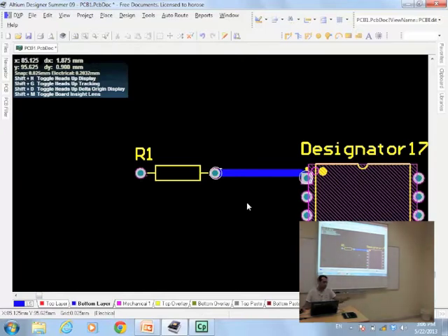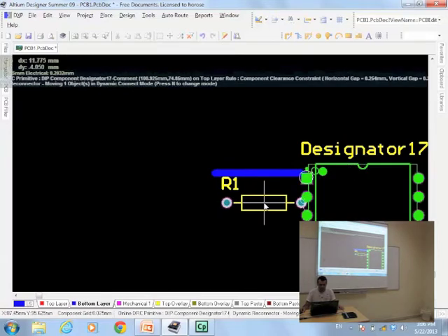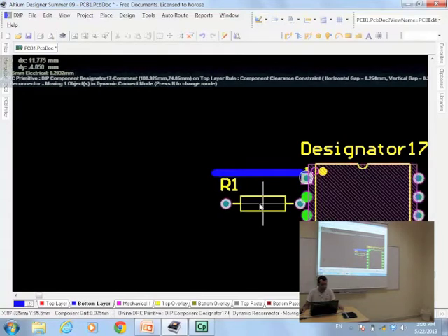Green in this software means warning. It has lots of things that you can define, lots of rules, the clearance of them, the size of them, all of these things. For example, I go close to this one, it turns to green, means oh, you are too close now.